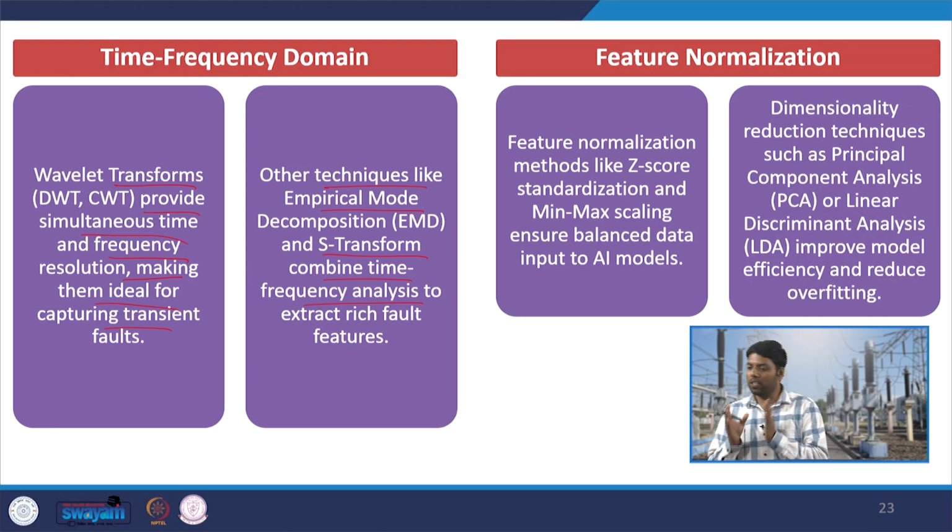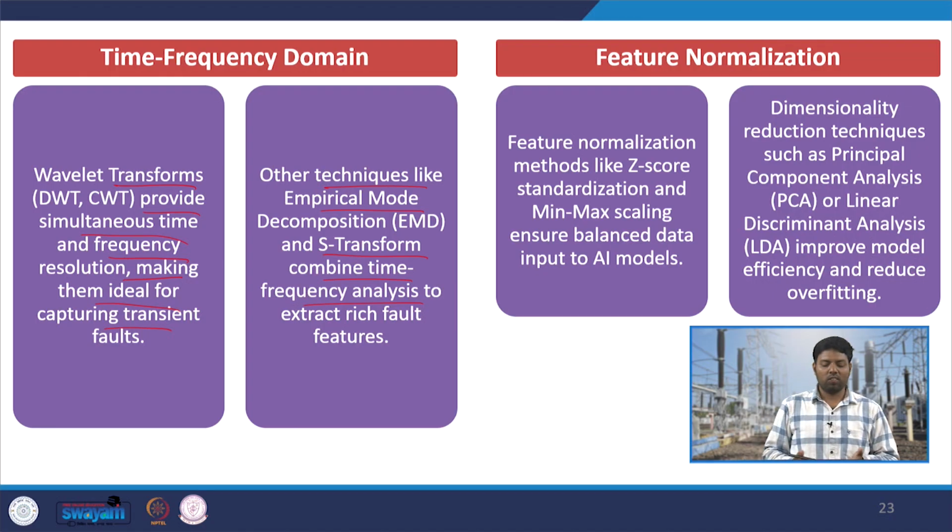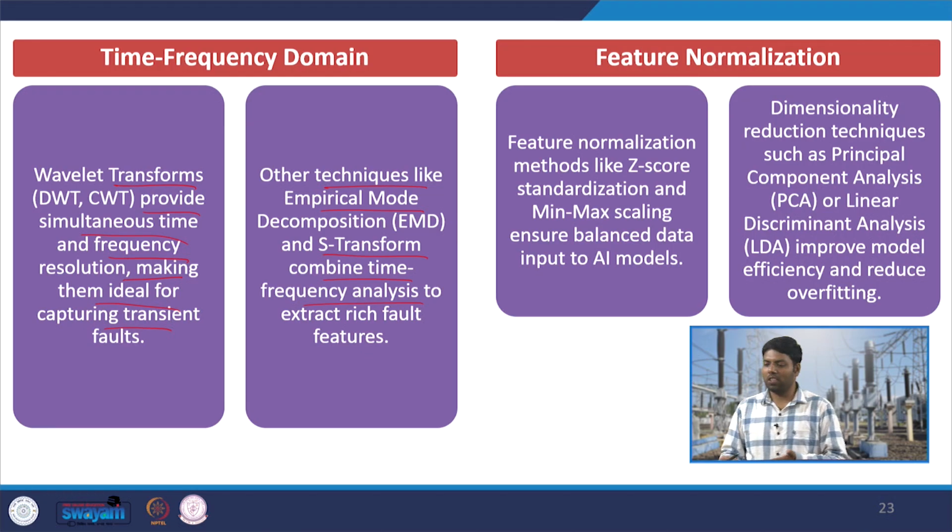If you are very specific about a few features that you want in your system, you can even extract a few features and keep them, then you feed the raw signal also into the CNN. So, that will also extract a few features, then merge all the features together and feed them to the fully connected layer for the classification. That is also good. So, if you are very specific about a few features, at that time you can extract those features, like time series features or frequency domain features or time frequency domain features, for your raw voltage and current signals.